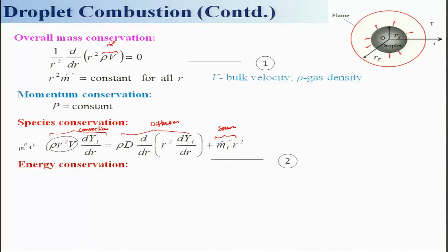If Lewis number is equal to 1, I can substitute rho D, because that basically means alpha by diffusivity, k_g by rho Cp into D. So, I can write rho D is equal to k_g by Cp. We will use that later on, okay.